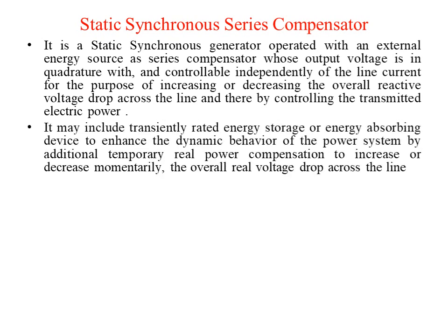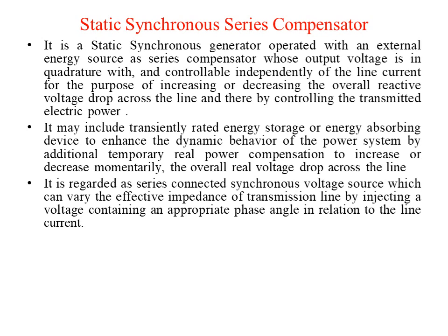It may include transiently rated energy storage or energy absorbing devices, just like we have studied in case of the static compensator, where we have an energy storage source, that is nothing but a capacitor present in the system. It enhances the dynamic behavior of the power system by additional temporary real power compensation, to increase or decrease momentarily the overall real voltage drop across the line.